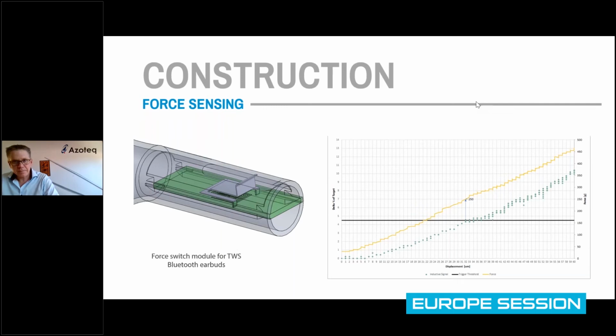External tuning capacitor. Yeah, external component. But the value of that capacitor is verified by design. So once you know the value of that capacitor for that specific layout on your PCB, then after that you can go to mass production with those values. With that particular PCB design and that capacitor value, you can go to mass production. It does not need to be tuned for every single unit that is produced.